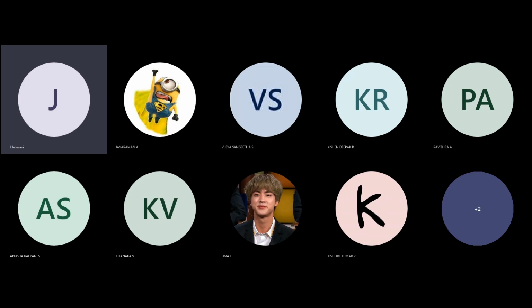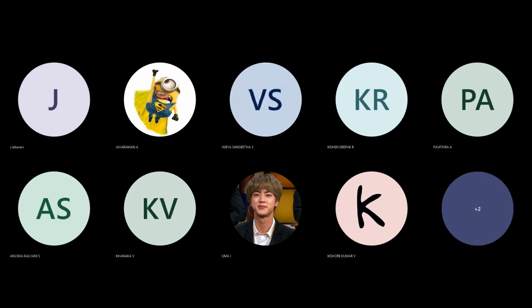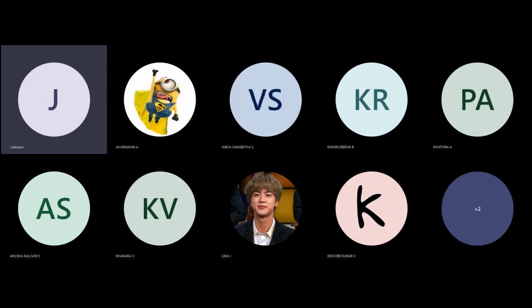In this water assisted injection molding technique, there are four different approaches. Water has a big advantage when compared with gas assisted injection molding. In general, when comparing water and gas, gas is compressible but water is not. So when the water is injected into the melt, the leading edge of the water forms a solid boundary or highly viscous membrane.